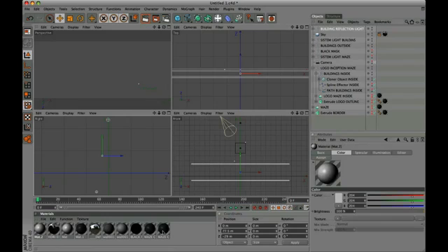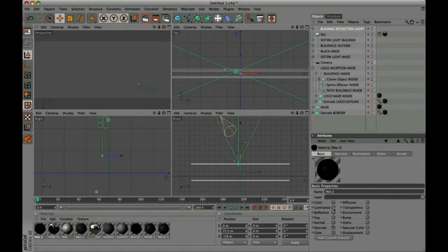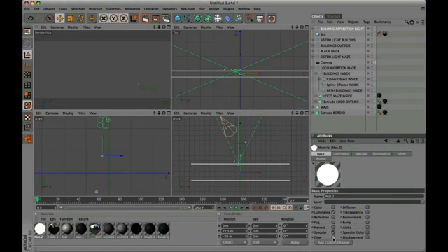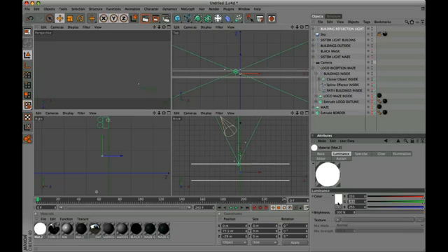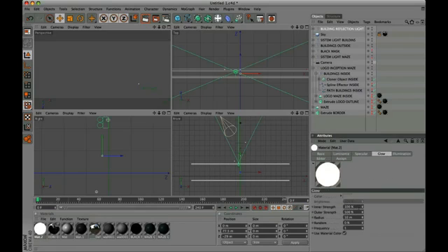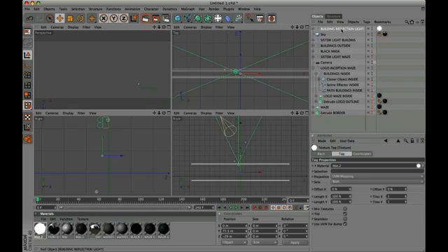Create a new material. In Basic Panel, disable Color, and activate Luminance and Glow. Change the luminance color, 238 and 188. On Glow panel, insert the following parameters: 80, 4, 180. We apply this material on our 2 cylinders, and view a render.